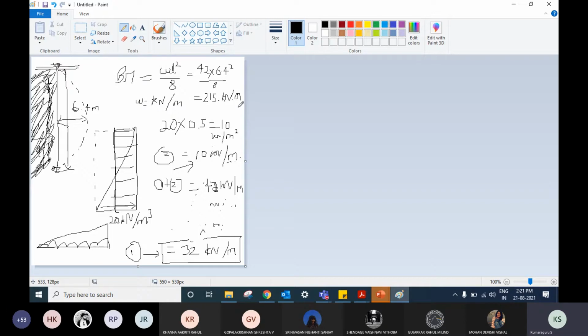Now this is our demand. Now we need to design the cross section to have a capacity which is equal or more than this, as simple as that. Usually, we need to target something more than this. One of the things, I did not take the factor of safety, like material load factor. This is the load value as such. We should be having a factor of safety.